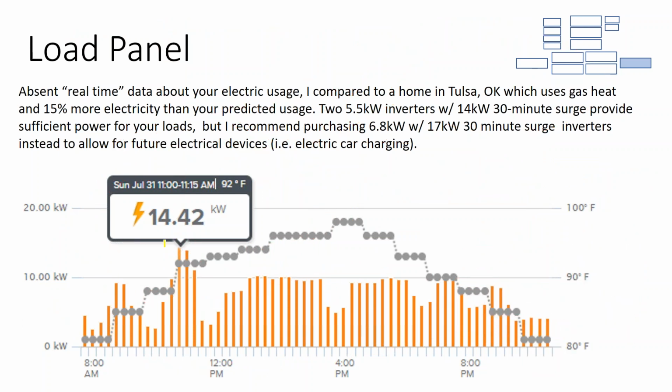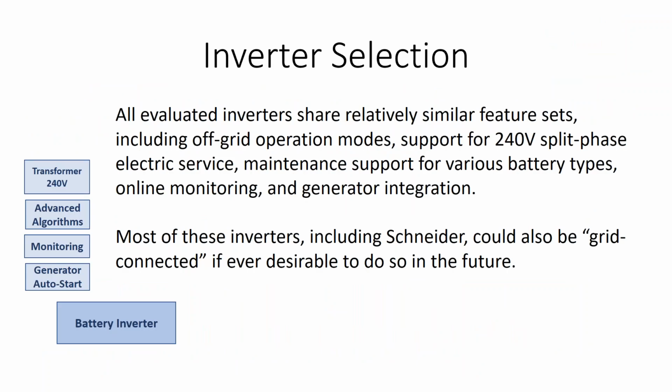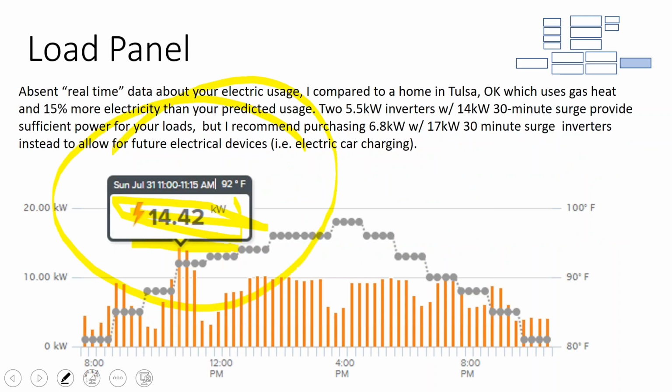So what this is telling me is my inverter output capacity has to be around 14 kW. And so when it gets time for inverter selection, we're looking for an inverter that has a 14 kilowatt output. It's kind of interesting. In a grid-connected battery-less system, you're selecting your inverter based on the size of your solar array. But when you DC couple, all the power goes into your batteries, and your inverter size comes down to how much power you want to draw out of those batteries.